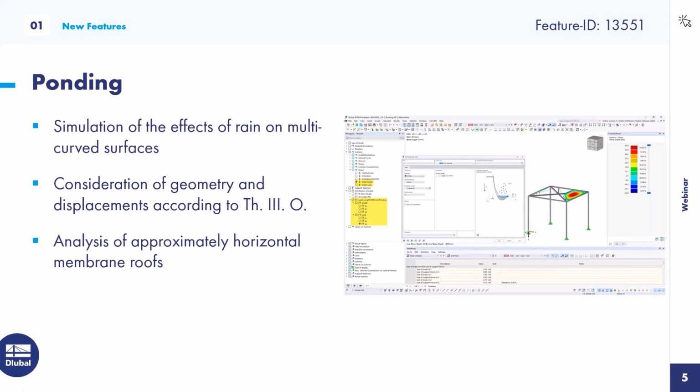Usually you, of course, want to avoid that rain will have a big influence on your membrane, but it depends on the shape and the pre-stress you can introduce into the structure whether you will have effects, maybe also together with a wind load or a normal dead load.